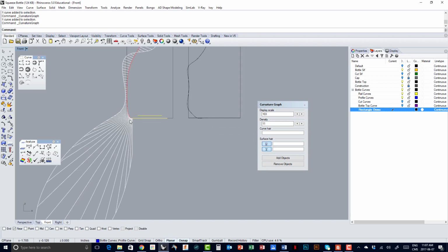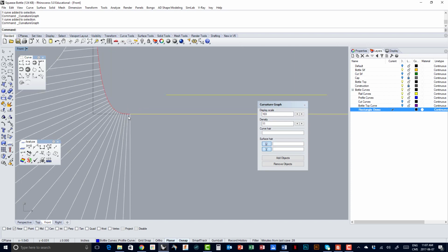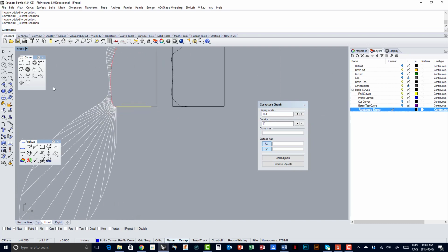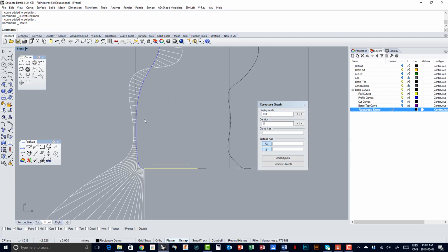Then it's positive, positive, and then when it snaps to a straight line, it becomes perfectly neutral, so you don't see anything. But in this case, it stops here, okay? But if you were to draw a straight line, for example, let me demonstrate this for you. Let's say I take a straight line and I turn the curvature graph on. Obviously, nothing happens because it's just a straight line. It's only visible when you see deflection in your curve.